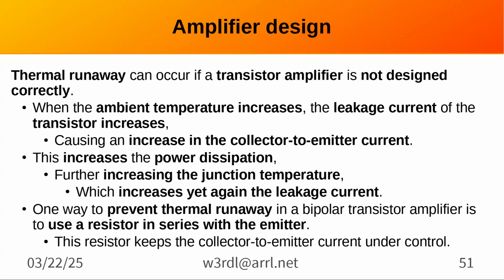So you can get a situation where you have thermal runaway because the hotter it gets, the more current it can pass, that makes it hotter. And so you have to put some limiting resistors essentially in the circuit. And this kind of describes where the leakage current causes part of the runaway. Normally it's just an emitter resistor, but that also decreases your gain and efficiency.